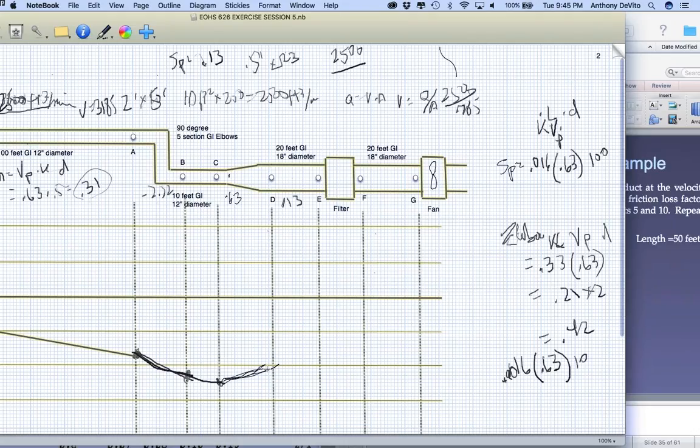Something weird happened here. The static pressure could actually be lower now to achieve what we need. But that makes sense because it's slower movement and it's a bigger duct, right? It kind of makes sense that it would go up now. Going from a big duct to a small one, I should have really done one where it went from a big duct to a small duct first because that's more intuitive, right? But if you stick with the formulas, it should work out okay.